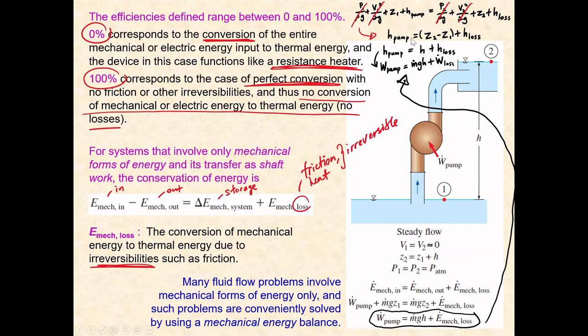So we can write a mechanical energy equation here for point 1 and point 2. Since we put a pump here, the energy from point 1 to point 2 is definitely added by the energy given by the pump. So we write here H pump. Mechanical energy at point 1 plus the energy coming from the pump equals the energy at point 2, plus a loss here.